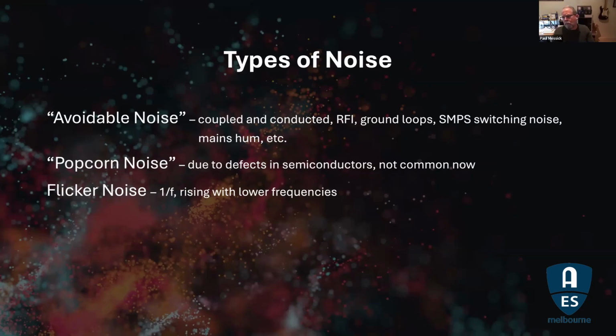It's less of an issue for audio because of two main reasons. One is the ear is not terribly sensitive to very low frequencies, and the most modern op amps have a very low corner frequency. But you might run into some kinds of design where this is an issue, so it's good to be aware of it. But we're not going to talk about that anymore either.